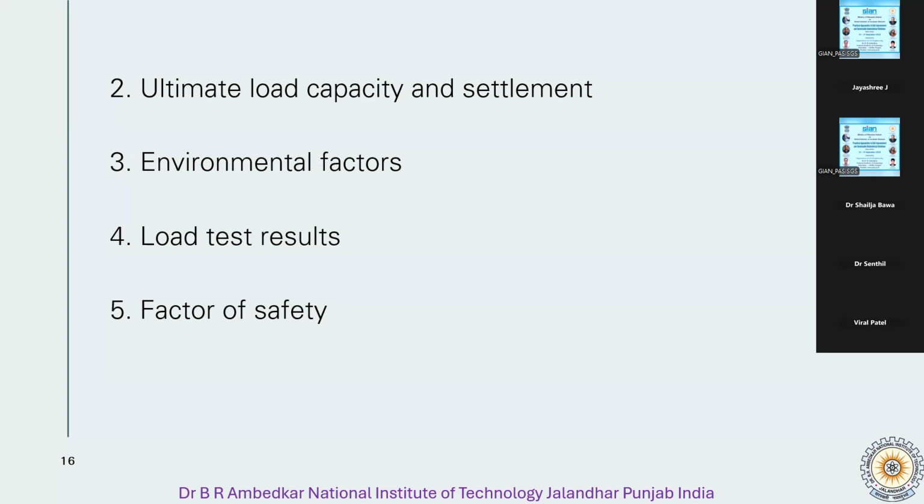The next point is the load test result. The settlement of the stone column at safe working load from load test results on a single column should never be used to forecast the settlement of the structure. Sometimes there may be familiar foundations or familiar structures in that area, and then you can take a fair estimate. But otherwise, the average settlement may be assessed on the basis of the subsoil data and loading details of the structure.